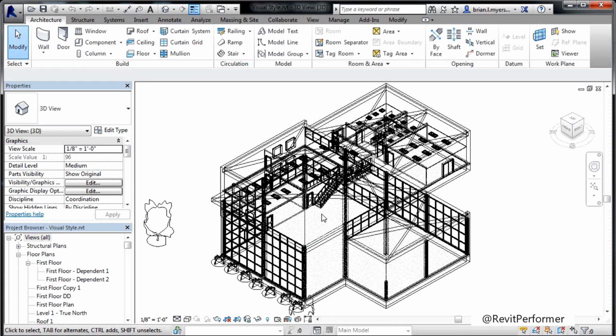One use is that you can select objects through other wireframed objects. If we had any other visual style, I would not be able to select the staircase or the doorway because the roof object itself would be getting in the way. Also, by having wireframe on, we can see the relationship between different objects underneath an otherwise solid object.